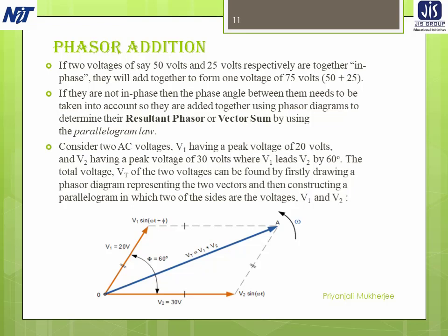And it is not necessary that the current and voltage phasors are drawn to the same scale. In fact, it is often desirable to draw the current phasor to a larger scale than the voltage phasor when the values of the current being represented are small. And if several voltage phasors are to be used in the same phasor diagram, they should be drawn at the same scale. Similarly, all current phasors in the same diagram should be drawn to the same scale.